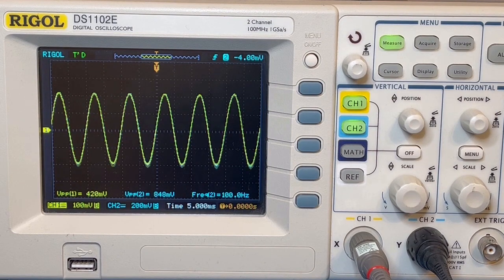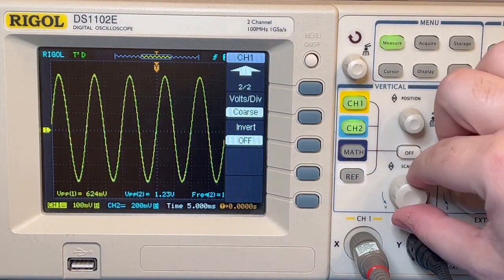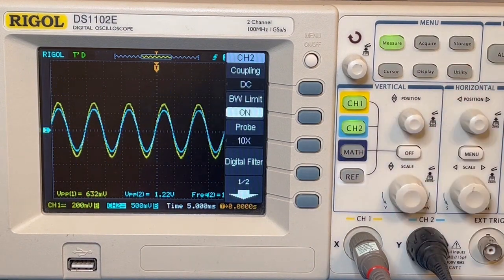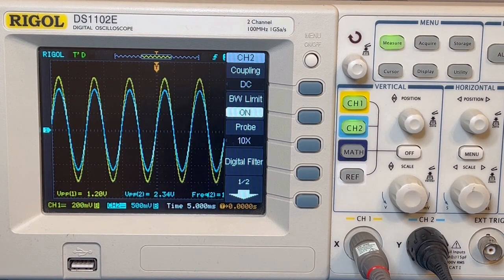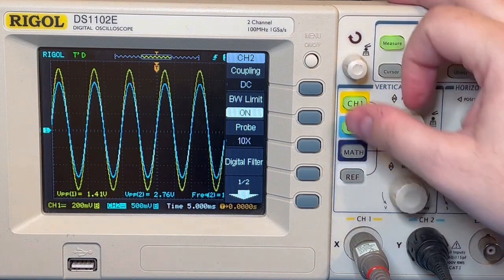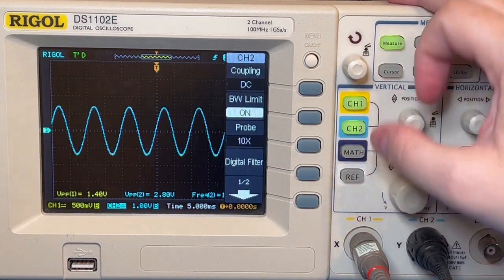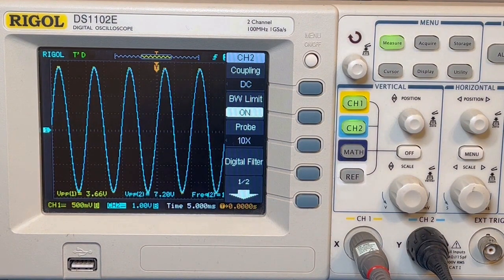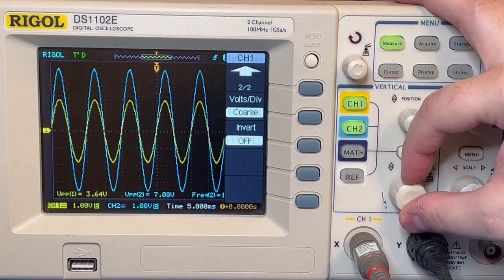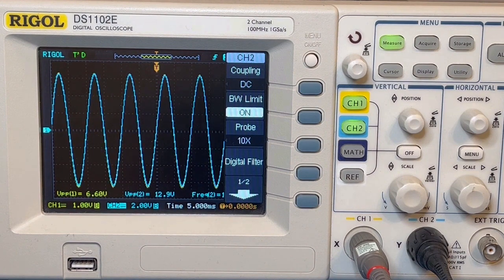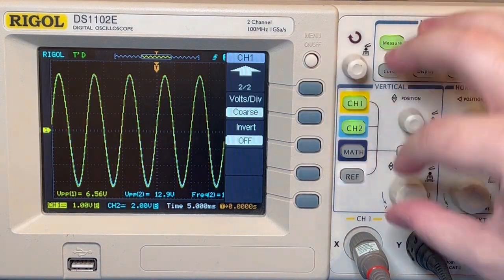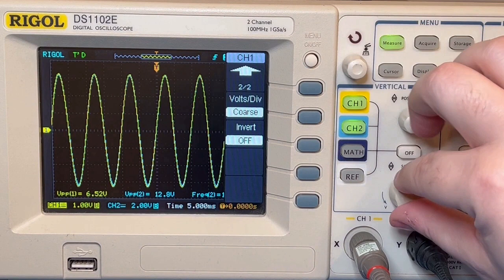Now, we're going to slowly increase the magnitude to see what happens at higher and higher magnitudes. See if we can see the effect we saw with the DC value, changing the oscilloscope scaling factors as we go along. Now we're at about 13 volts output. Everything looks pretty good, just like it did before. The signal's a little cleaner because we're now further away from the noise floor of the oscilloscope.